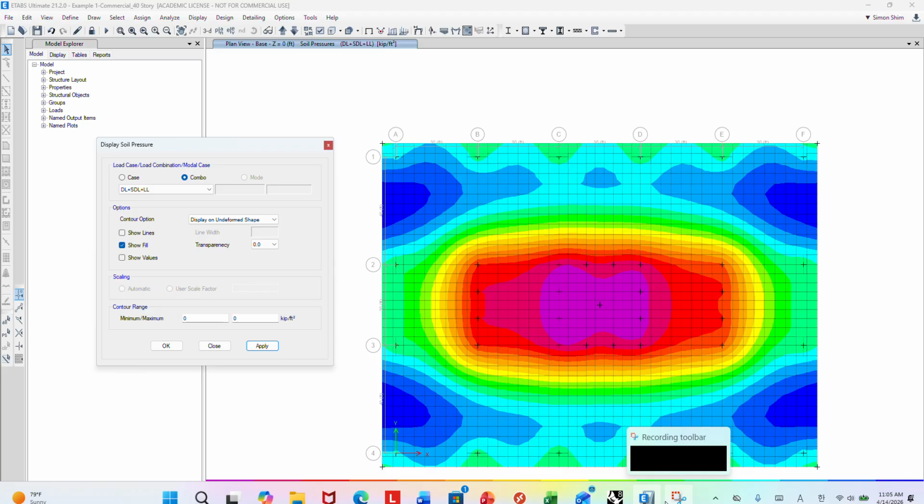But at the building scale, the soil stress is not going to be uniform. This is the building and your loading, right? We have various loading intensity from the columns and walls, so the soil stress underneath the mat is not going to be uniform, right? What you see is, based upon your total loading from the walls and each column, the soil bearing stress underneath. So this is actually a contour.